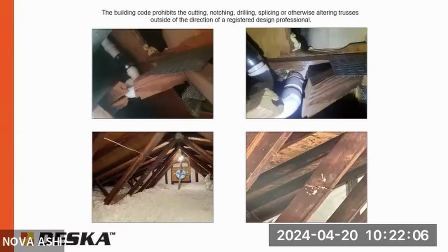Fortunately, in residential construction, whether it's attic roof trusses or floor joists, you have a lot of them. So even though by cutting one member of one of them you're decreasing the capacity of that member by a lot, in this house you probably have 20 more. But if you cut several of them, then it's even more serious.